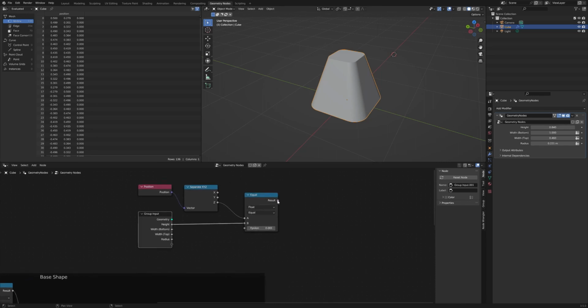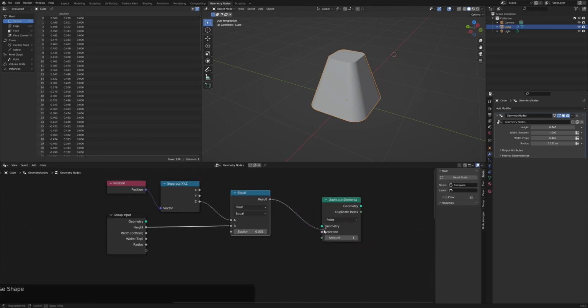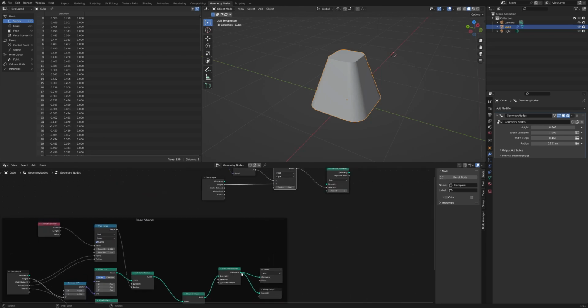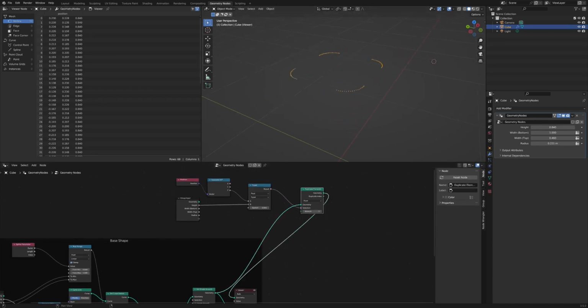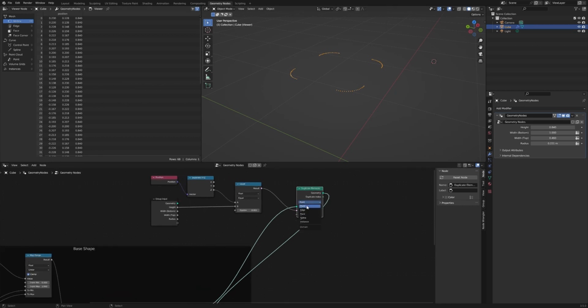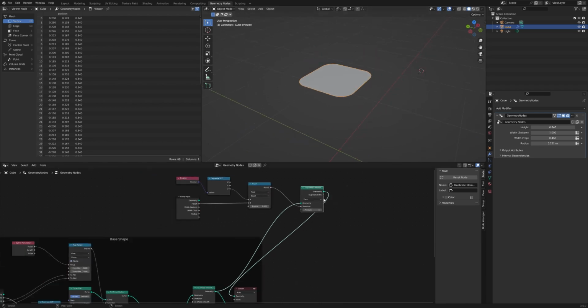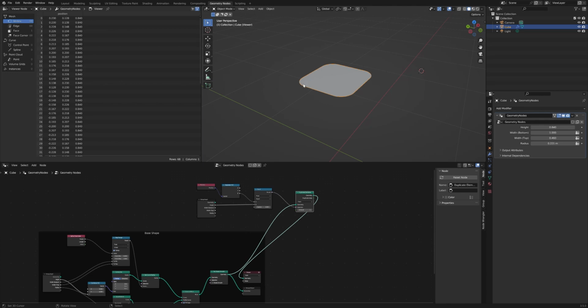And then the result, you'll notice, is this thing called is pink, and we can actually duplicate elements. And in theory, we could just extrude directly, but I quite like having a little duplicate of this just so it's a separate object. And we're going to say, I just want to duplicate this selection of all of our geometry. And then what that will do is, you'll notice, just get our vertices, which is not ideal. We would want more than that because I've clicked point and not faces, which is the thing we actually want to duplicate. So now if I click face, we end up getting the whole face instead of just the vertices in the corners.